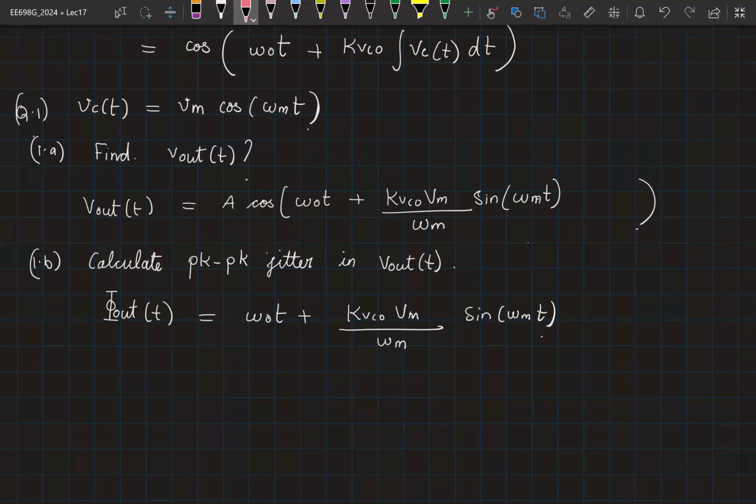Right? Now this is your operating point. This is the ideal waveform that is linearly increasing with respect to omega naught, which forms your operating point. So this additional quantity here is what we generally would have called phi n, right? Phi n if this was completely random in nature. Another term for this additional small signal is also phi x, for excess phase.